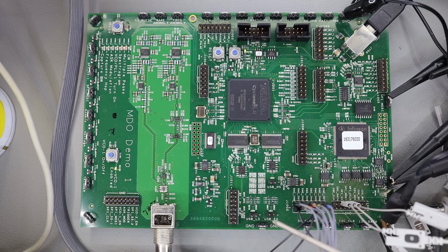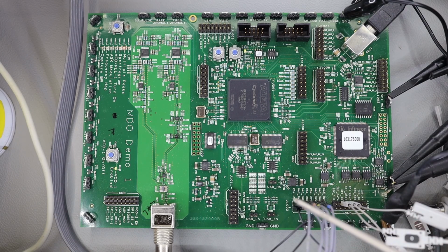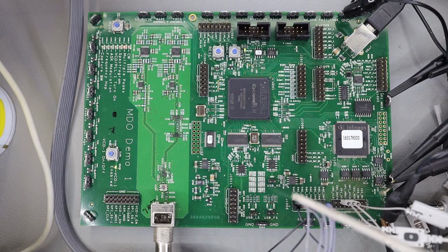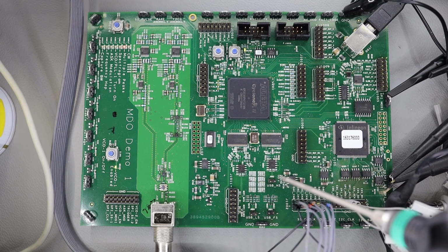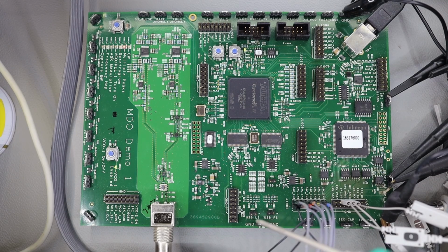On this side you have high speed signals, for example MIPI, or you also have USB LS, USB FS, and USB HS. Probing USB HS is going to be interesting. We will need 2 probes because I do not have any differential probe, so we'll learn about probing as well, how to deal with a situation where you need a differential probe and you don't have it. So our oscilloscope will help us. Only my 8 GHz oscilloscope can decode USB HS, and the normal USB speeds my MDO3000 can also decode. The RTB2004 cannot decode USB at all.